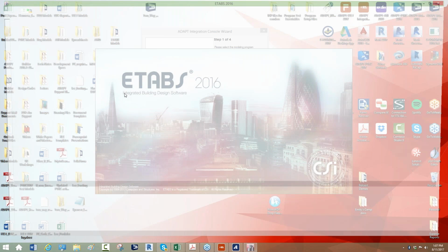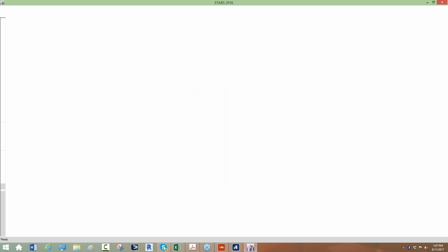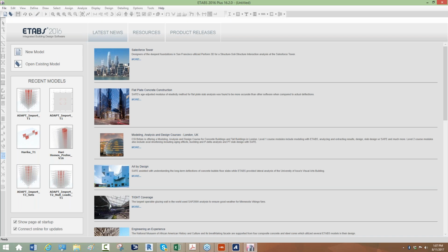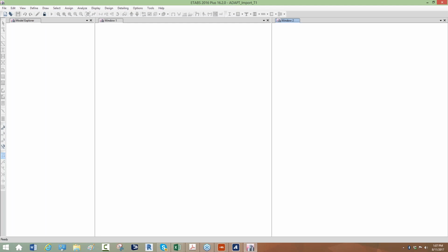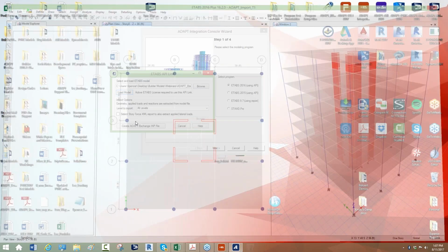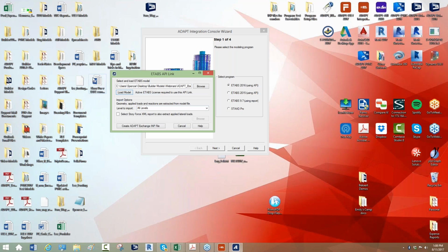The user doesn't need to close the file. If you close it, it could interrupt the extraction of the data. So just allow the program to open Etabs, and then it will automatically close Etabs when it's completed. Files that are heavier in terms of data and load combinations, just a heavier model in Etabs, will result in longer runtime for this particular part of the application. So it could be seconds or it could be minutes depending on how large the Etabs file is. And we'll just go ahead and wait. So that's done. Etabs is closed.